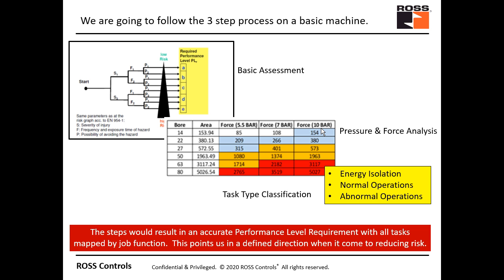It could even be cleaning. So we have to look at how we want to treat these abnormal modes of operation. And so we need to look at every job task and every mode of operation, and we also need to look at every energy source in order to have the best possible risk assessment.